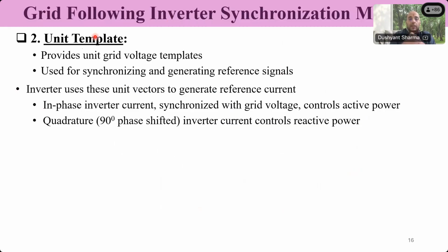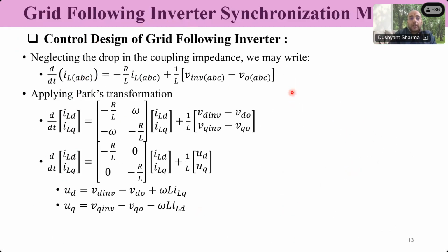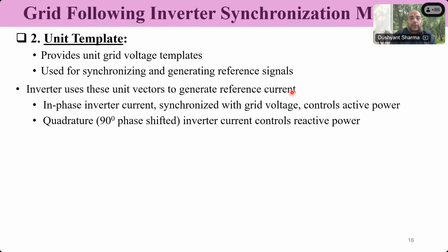So what we do, we have the time varying ABC 3 voltage signal, which is the bus voltage reference, Vbus. Now these 3 bus voltages, VA, VB, VC, if we can divide them by their peak, then we'll get 3 waveforms whose peak will be just 1 and bottom side it will be -1.